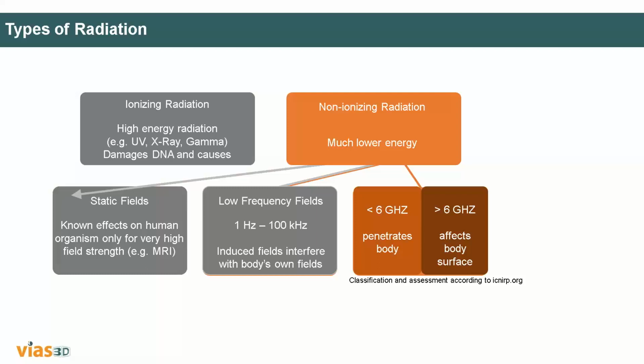See, if you increase the frequency, you get high bandwidth, right? You get 1, 2, 3, 5 gigahertz bandwidth, because as the frequency increases, you get more bandwidth, which means you can transfer more data. But what is the practical problem? If you are increasing the frequency, your wavelength becomes shorter and shorter. Your range is limited. That is the most important problem.